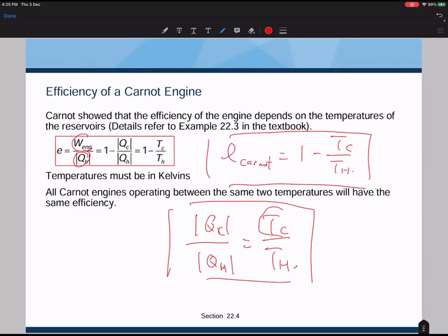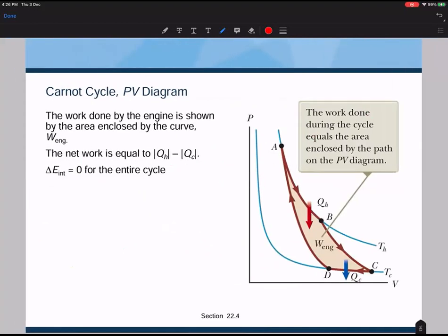So does it mean that we could run the heat engine using a Carnot cycle? The answer is no. As explained in the video, you need to have reversible processes for the Carnot cycle. For example, in the isothermal heat transfer processes, how could you transfer heat energy in a reversible way? You have very small temperature difference, and that means infinitely long time.